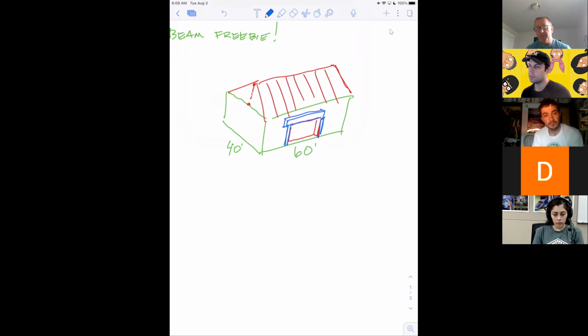The beam sits on top of the two posts. And now all of this load from the snow that's sitting up here coming down sits on the beam. And of course, as we said yesterday, doesn't that beam want to bow down a little bit? So that's why we got to know something about it, because those can bow down enough that the garage door won't open, or the windows won't open or whatever. And then of course that transfers the weight to the posts.